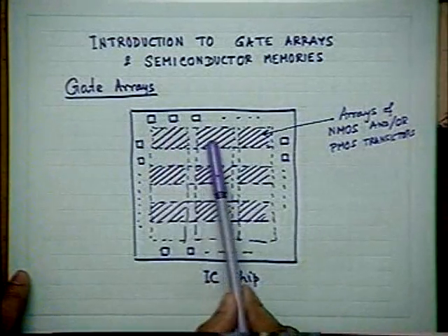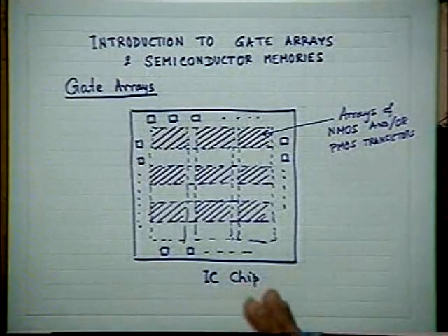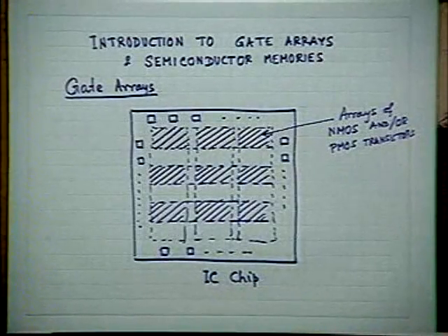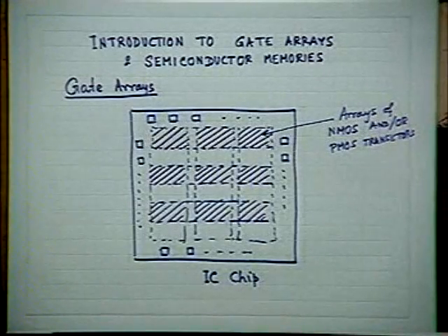Please see that I have divided the chip like this, where the violet shaded regions occupy the maximum area. The chip is so divided that these regions hold an array of identical NMOSFETs, or an identical NMOS and PMOS array. So this is a prefabricated slice. I have shown only one chip, but think of the whole wafer, which contains hundreds of exactly similar chips, called a step and repeat array in 2 dimensions. I am showing only one single chip out of the array.